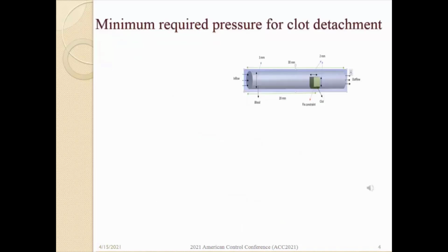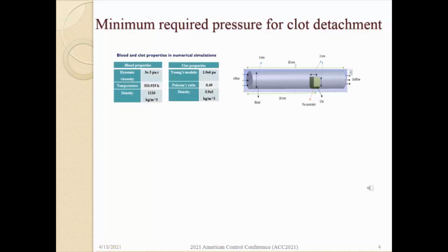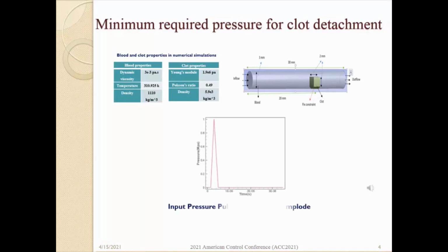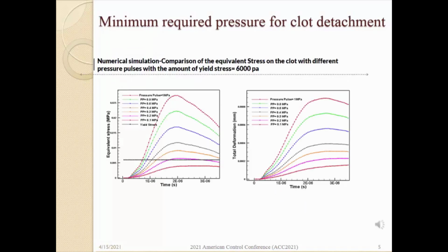As I've mentioned before, this study is related to the vessels which are connected to the pulmonary veins, and the clot dimensions are considered according to the vessel dimensions. Using these parameters, the blood and clot are simultaneously simulated, respectively as a flow and a solid. The inflow pressure of the vein inlet is specified to calculate the amount of pressure on the clot at various times. In order to have an exact numerical simulation which covers the relevant features, good quality mesh generation is necessary. In this study, tetrahedral elements are used for the entire field meshing.